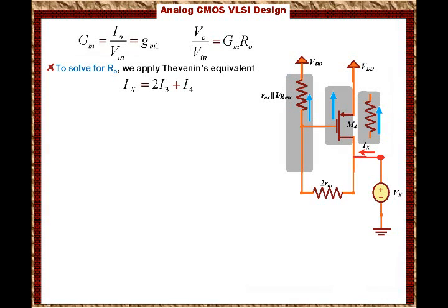So transistor 4 has two currents, the current going through RO4 and the current that is reflected from M3, which is the same as M1 and M2, right? So the current going through M3 is the same as M2 and the same as M1, and that current is reflected to M4 plus the current that is flowing through RO4. You see, so that is kind of interesting.